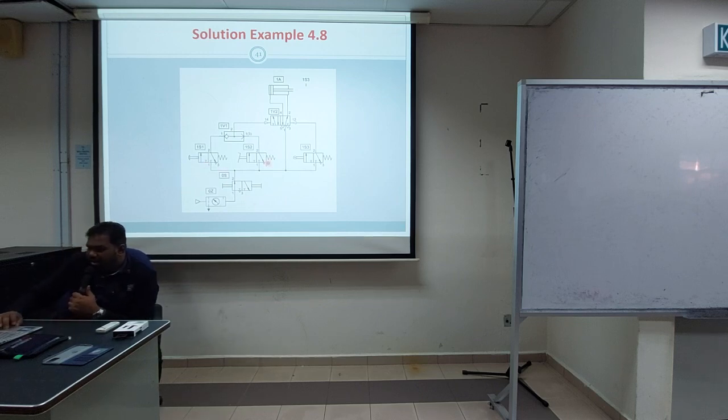Okay, you can look here. You have either one input, so you use an OR valve. You have the push button input or the foot pedal. This is the picture of the foot pedal. So either one is present, and it will send a signal to the valve and your cylinder will extend. When fully extended, it hits the 1S3 roller valve sensor. If it is only halfway extended, this will not turn on. Only when fully extended will 1S3 turn on, then this turns on. It will send a signal for it to retract.